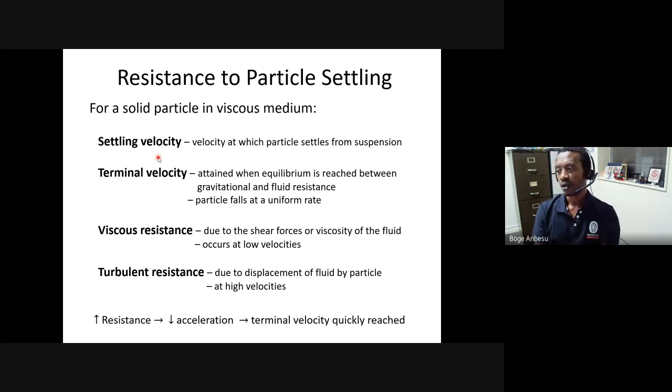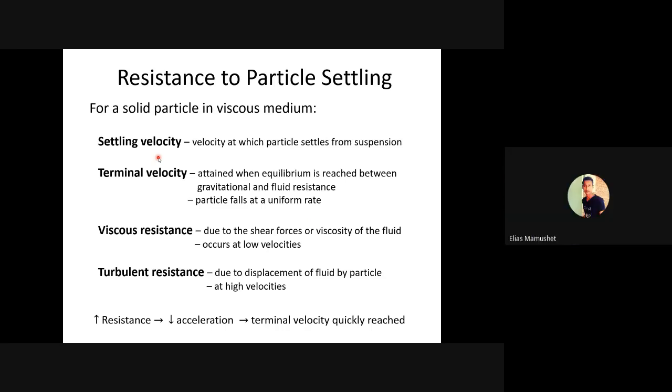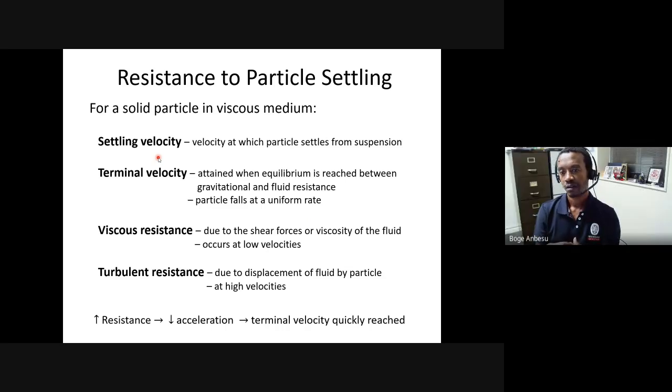If I have a viscous medium, for example, instead of water, you can use dense media for separating particles. If that medium is too viscous, again, you're making it difficult for particles to move, and viscous resistance may be prominent in a typical equipment, or maybe it's actually turbulence. When a particle moves in a liquid, it displaces the liquid, and that may also present resistance to flow.